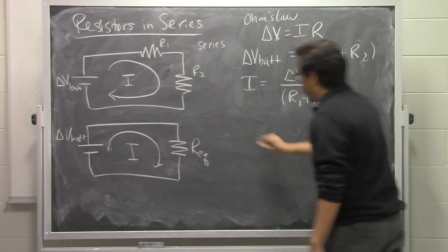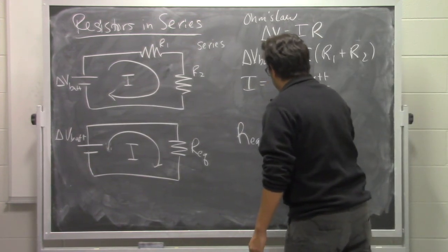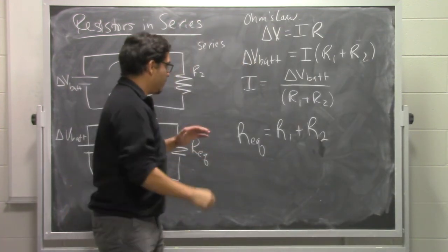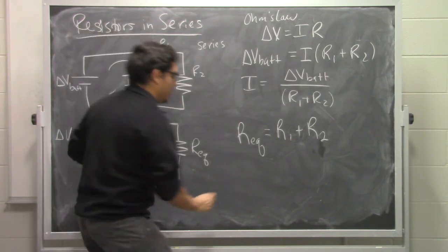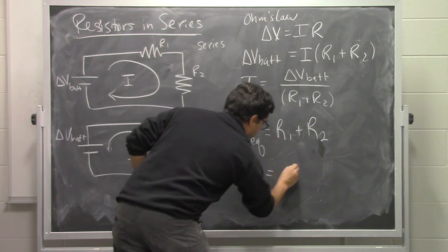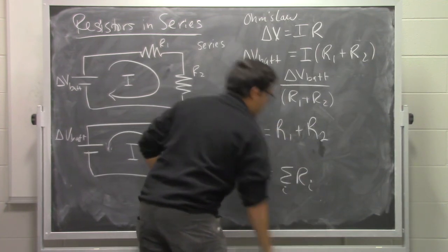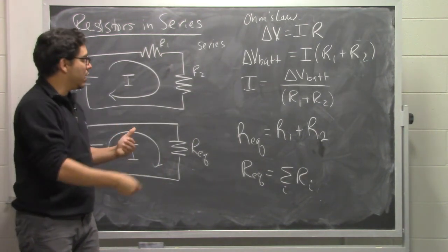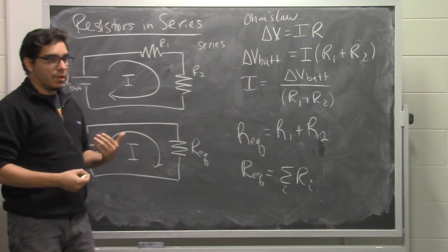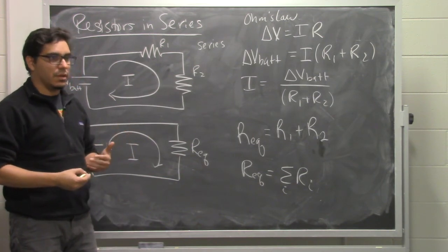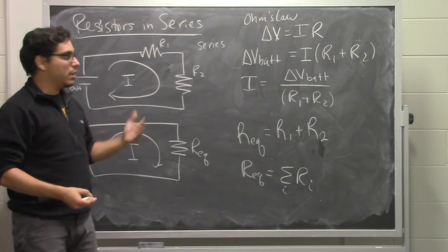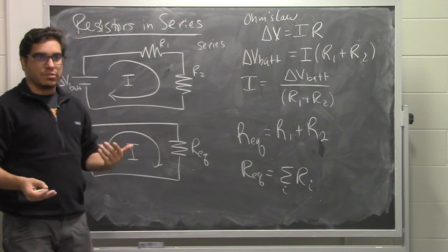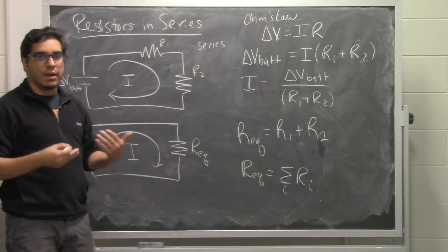And we can do that if, in series, resistors add just like that. That is, for every resistor you put in series, the total sum of the resistance tells you about the equivalent resistance. So they add up in series, just in order. Now, we can think about that from a microscopic perspective if we think about the resistors as being essentially just longer. Having these two resistors is essentially like having one longer resistor, and the longer resistor from the microscopic perspective tells us that we would have a higher resistance.